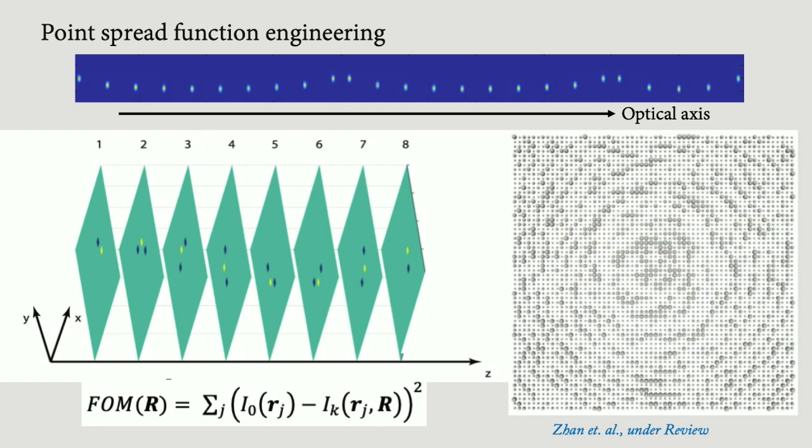This is how we came up with this figure of merit. We put it in our software, and this is what comes out. It spits out these spheres. I would like to point out this is probably the largest-area optical element anyone has designed with inverse design. Previously, people have done probably 1 micron or maybe 5 micron squares. This is 150 micron square, and that can be done because we are using Mie theory. There is no way you can do 150 micron square using solely Maxwell inverse design. But of course, there is a penalty, which I'm going to talk about: we have just spherical shapes.